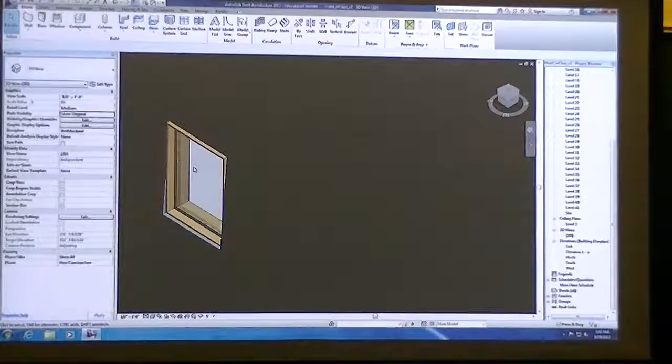You might want to develop your second room type if you haven't already. And then I want you to start placing exactly how you're going to get 50 guest bedrooms and 50 townhome share units along your floor plates. Start to place those everywhere so that eventually you'll have some leftover space that we can start to develop atrium spaces. And remember to carve out spaces for your stair and elevators. Just throw those into your design for now for planning purposes.